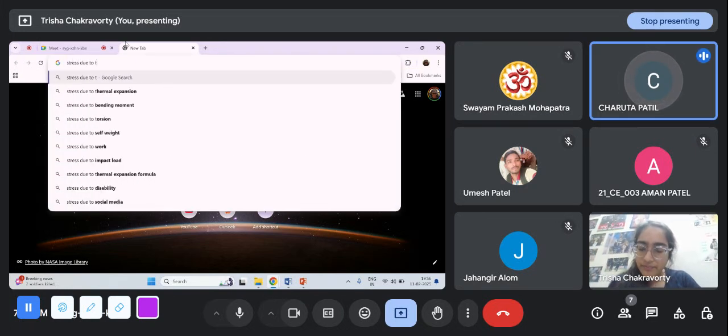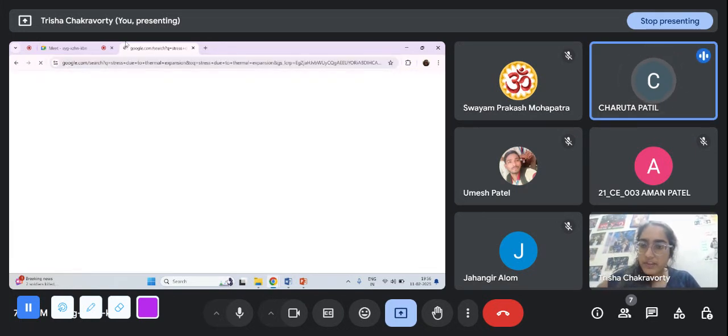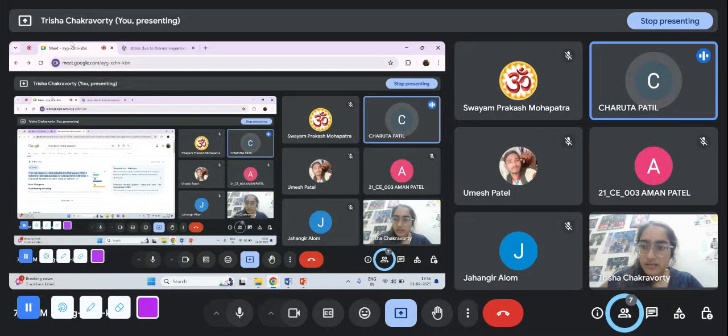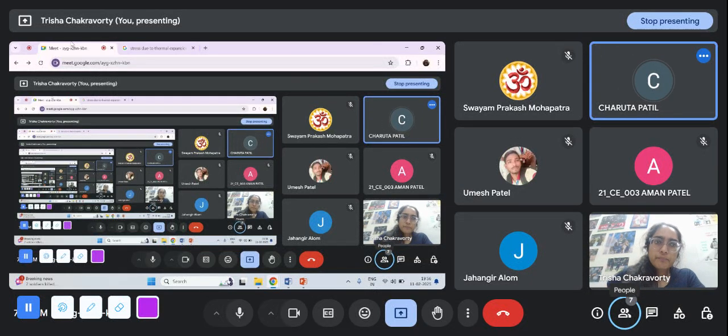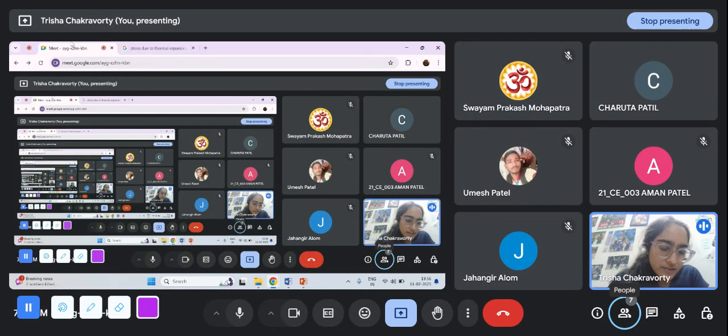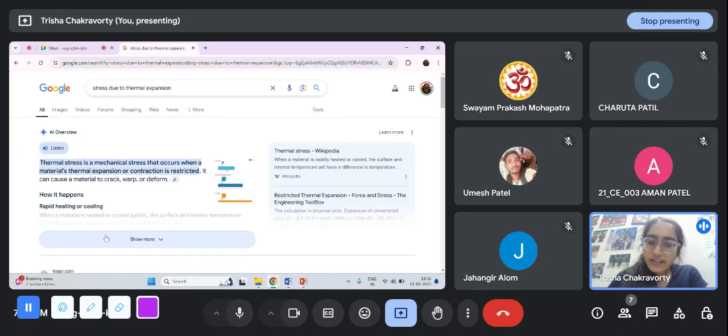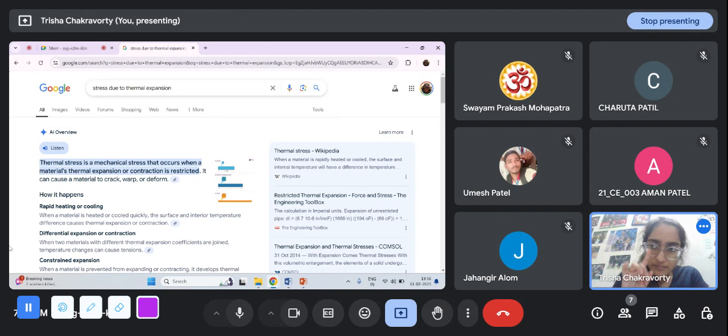That is the formula, alpha T L divided by summation of k square L upon AE. Forget the k square L upon AE so far. Initially, just first think of alpha into delta T. One second, give me 2 minutes.